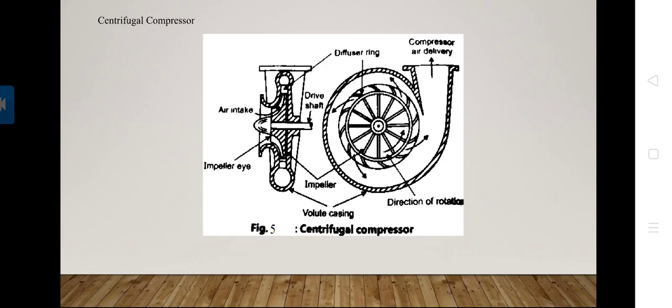The efficiency of this centrifugal compressor is high, and its part load efficiency is better than other compressors. It is also directly coupled to the motor or prime mover, and it can be conveniently used with R11, R12 and R13 and ammonia.